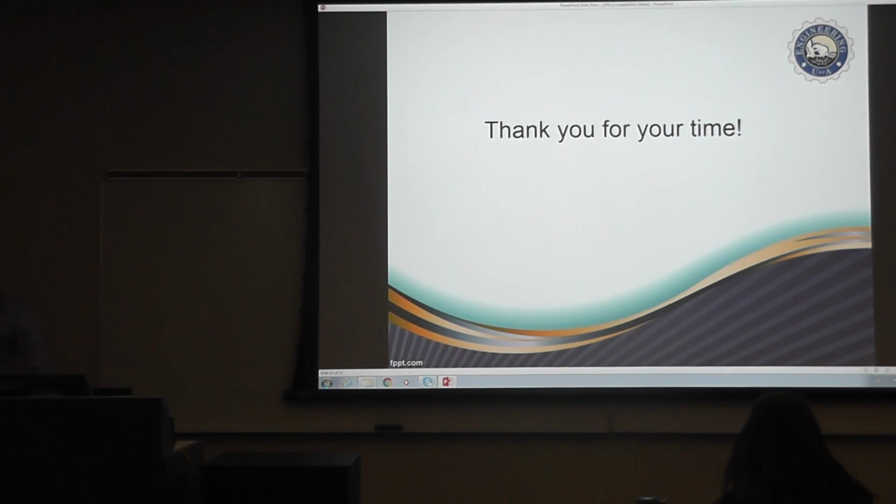Pretty much. Every company has, when we looked in those drawings from Dialogue, there were about 60 different embedded plates. If you go to another company, you'll get more plates. And everyone has their different idea of what plates should be like and how they should work for certain loading conditions. And so it'd be easier to standardize that and say, look, these are 50 embedded plates that will encompass 80% of the loading conditions that you have.